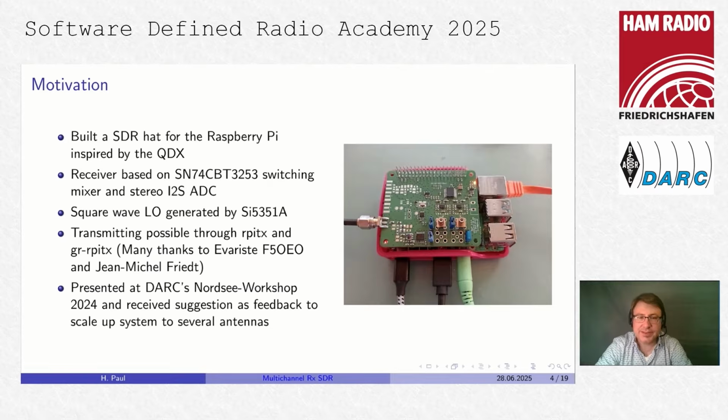like the original QDX, square wave local oscillator is implemented using Silicon Labs' Si5351A. And it's also possible to transmit with this board, basically through RPI-TX and the corresponding GNU Radio block for that. Many thanks to Évariste and Jean-Michel, who are also frequent participants in the SDR Academy.